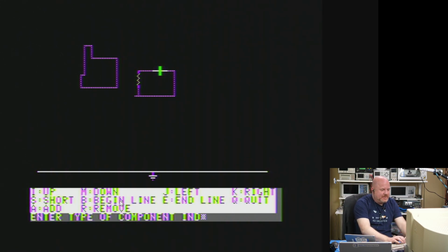So let's see what other components we can add. So I did IND, so that's probably going to be an inductor, parameter value. I'm just going to say 1. Okay, if you call that an inductor. So now I wonder how we can get a transistor though. I wonder what they would call it. So type of component Q, BJT, PNP, or what did I just do? NPN. Okay.